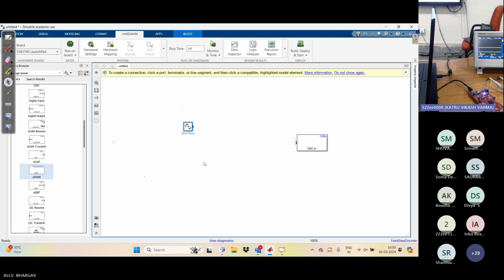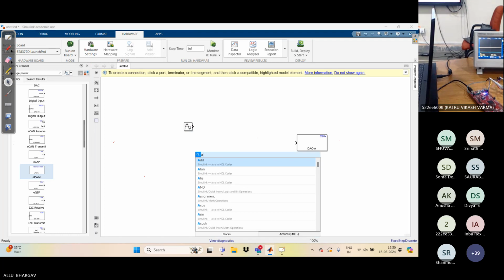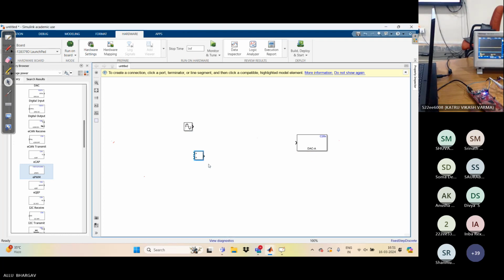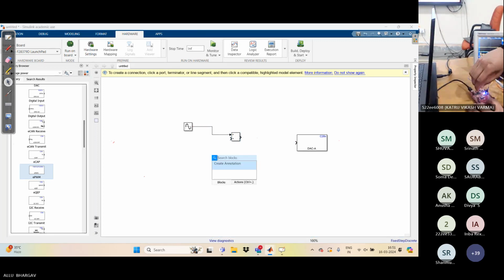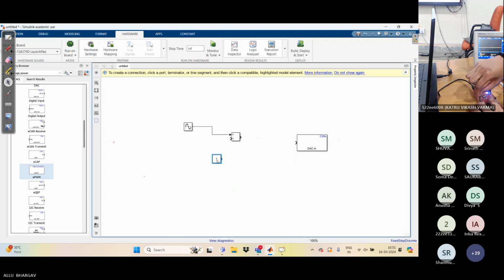And now I have to shift the signal. Our sine signal is 1 amplitude, so we are adding one more 1 to make its reference value from 0 to 1. So the whole signal peak value will be 2, the reference value will be 1, and the negative peak will be equal to 0.